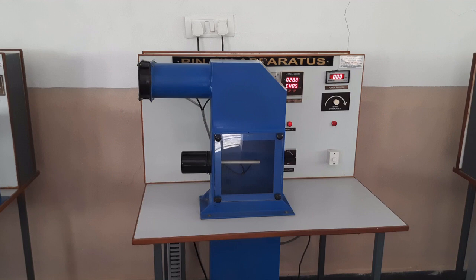And observe the temperature values at the surface of the fin. The surface of the fin reaches room temperature. So after reaching room temperature, let us start the experiment in forced flow condition. Observe here that the temperature of the surface of the fin has almost reached room temperature. So now I am conducting the experiment in forced flow conditions.